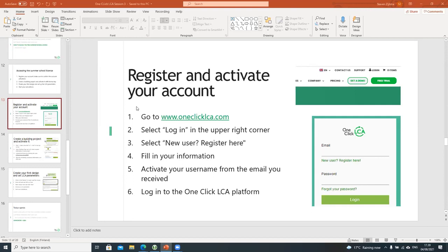Nawapan asked if we can use the EPD number for the IFC material names in the Excel sheet. If you have the EPD number, it would indeed be possible to already link these automatically to options in the database. Just make sure you have written it correctly in that case. Usually you can copy the EPD number directly from the EPD, and that would always be the best way to find it. I see Fernando had asked it already. Thank you.